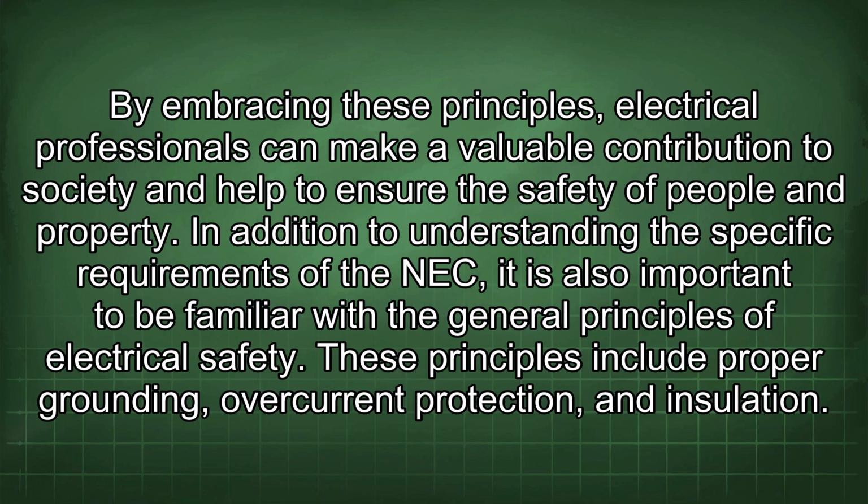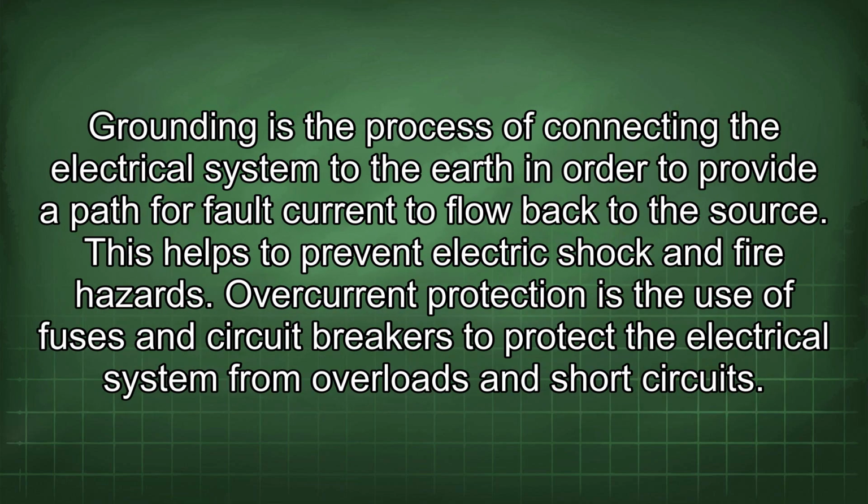In addition to understanding the specific requirements of the NEC, it is also important to be familiar with the general principles of electrical safety. These principles include proper grounding, overcurrent protection, and insulation. Grounding is the process of connecting the electrical system to the earth in order to provide a path for fault current to flow back to the source. This helps to prevent electric shock and fire hazards.